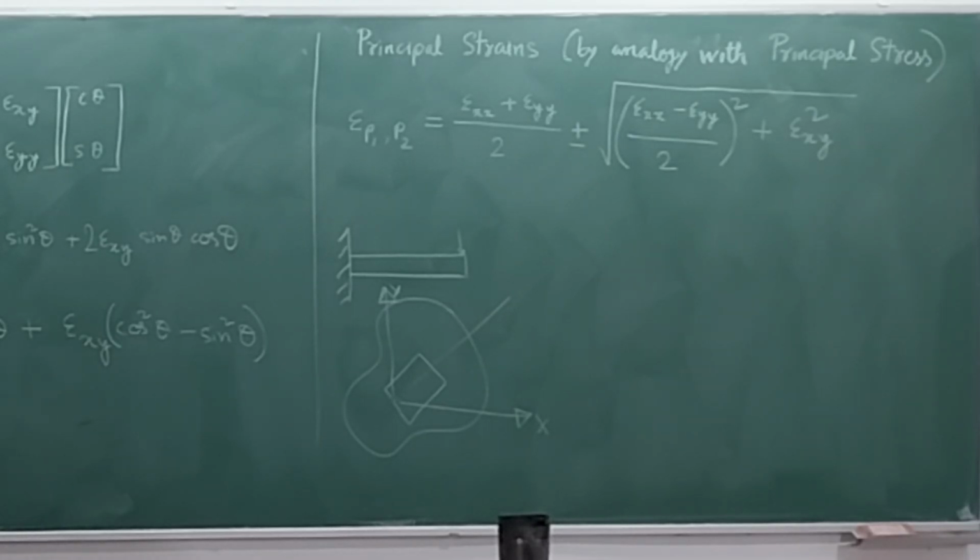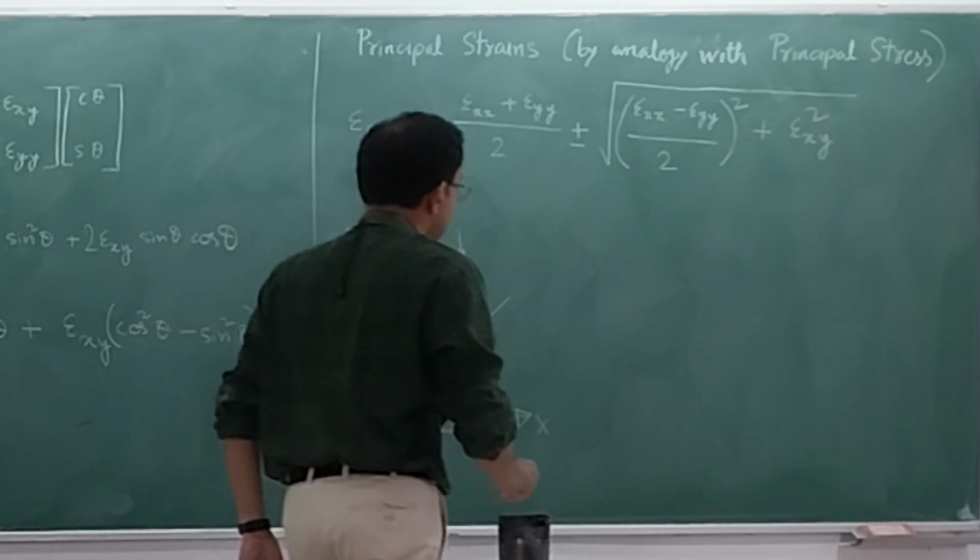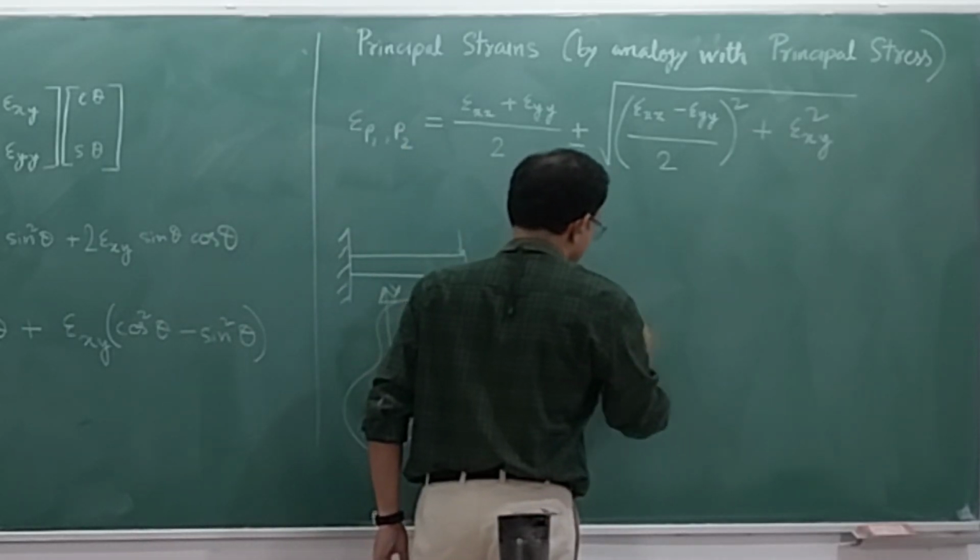Two strain gauges. Okay, two strain gauges. So actually what is done is some combinations of strain gauges are used. Usually 3 strain gauges are used, and they are arranged in various types of combinations. Some formal names are there: delta combination, star combination, all these things. Basically what they are doing is arranging the strain gauges at different angles. The names are just fancy names. So you have strain gauges which are oriented like this. This is one particular orientation.